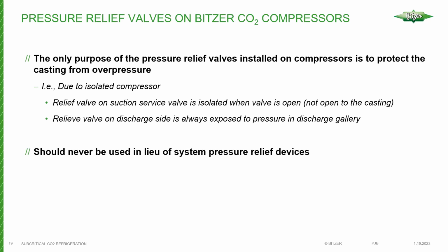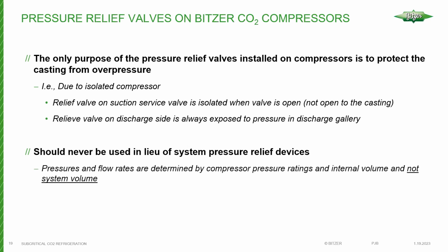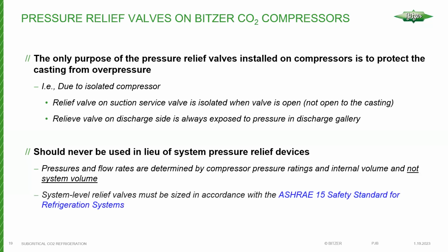So these relief valves, because they're there specifically to protect the compressor from overpressure, should never be used in lieu of system pressure relief devices. The flow rates of these relief valves are based on the internal volume of the compressor, and not the system volume. So this is a very important point.